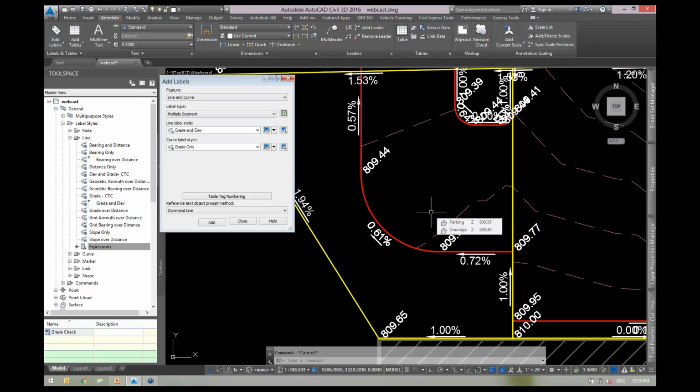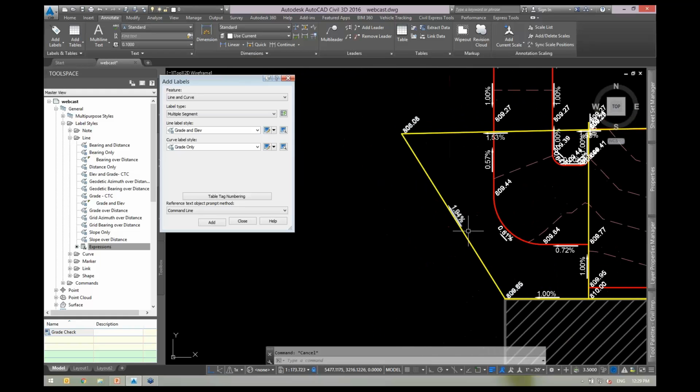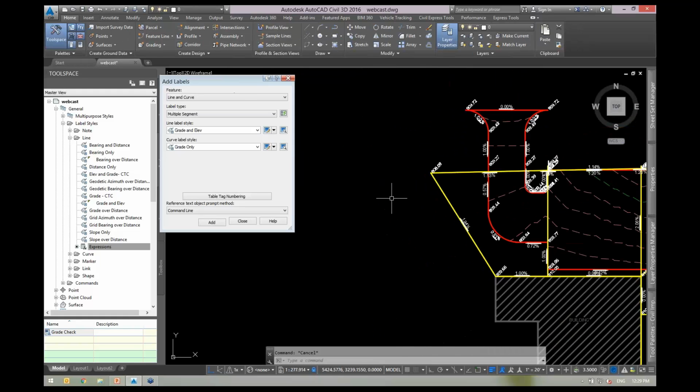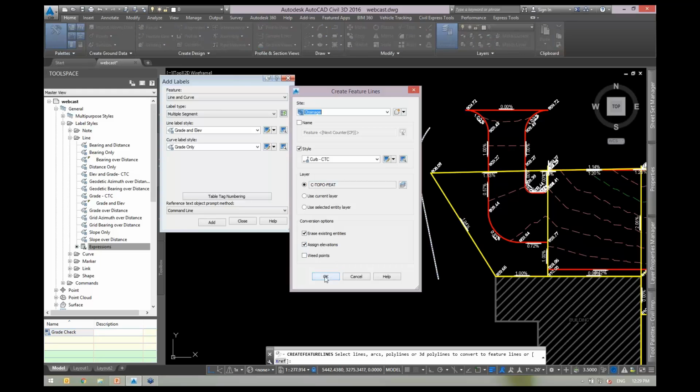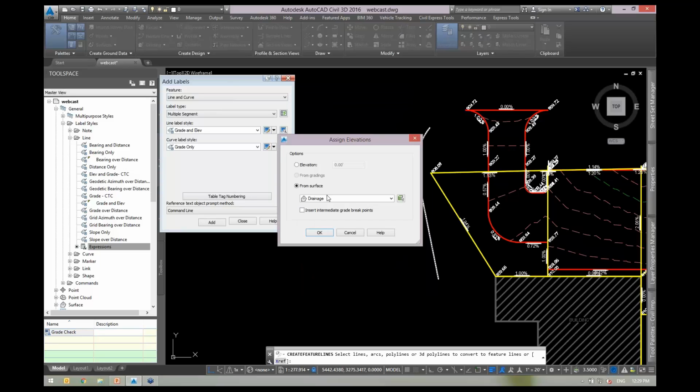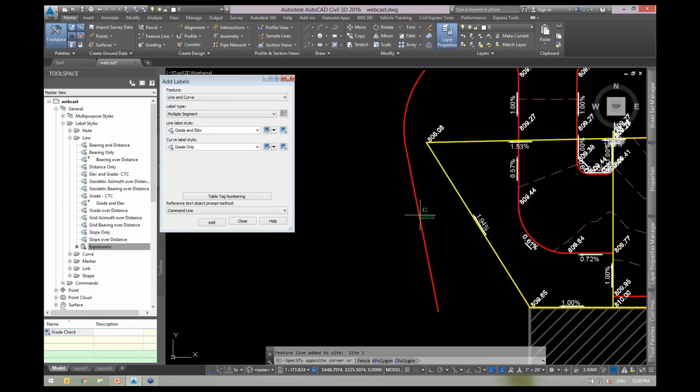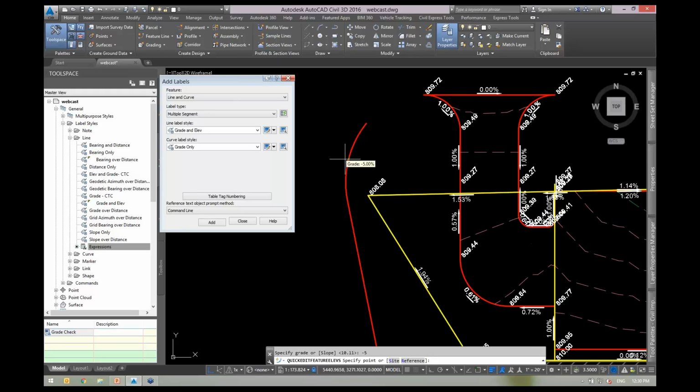And now what we're after is getting those same kind of curves to behave the way we want. And in fact, let me make this a little bit simpler. We're going to come out here, just do a basic polyline. Perhaps this represents a ditch or something. We've got an arc on it right there. And let's turn this into a feature line. And we'll give it an elevation. We'll start at 850. Okay. Put some different grades on it. We'll go down at a -5 and then down at a -5% there as well.